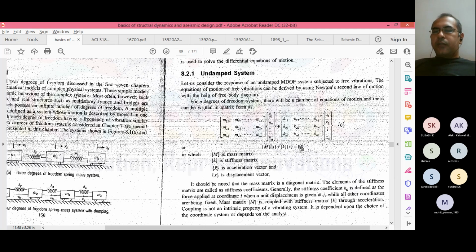No external force is applied for the vibration of the building, so the building will vibrate as per its fundamental properties. That's why it is very important. This is what we do for calculating the time period of the building in each mode; we'll see what a mode is. That is a very important deduction: we do the eigenvalue solution using this formula only. You need to do this manually to get the answer.